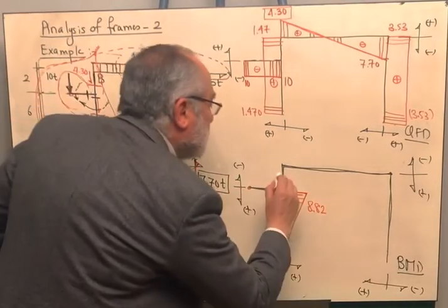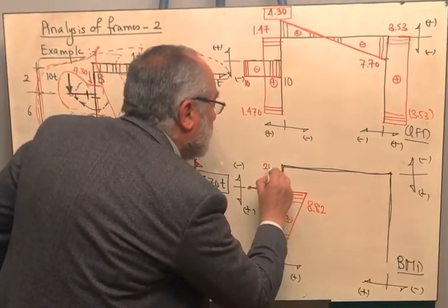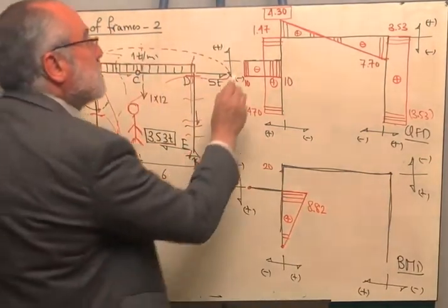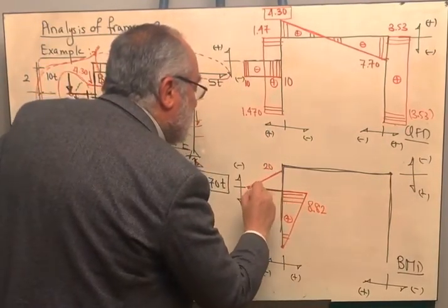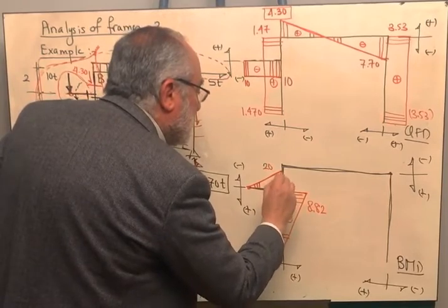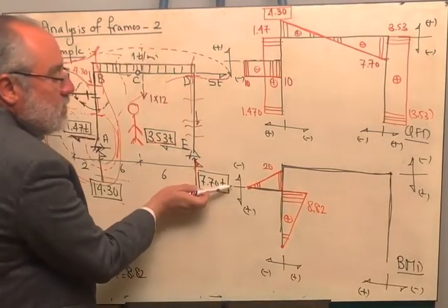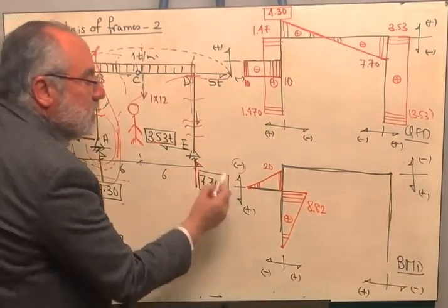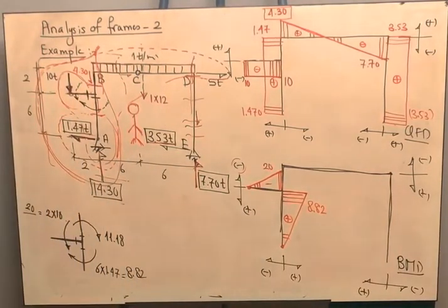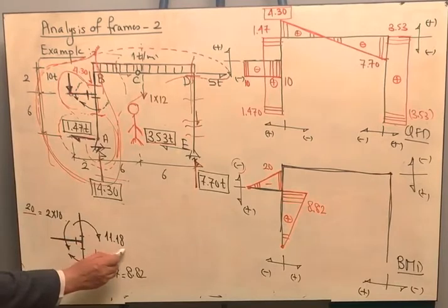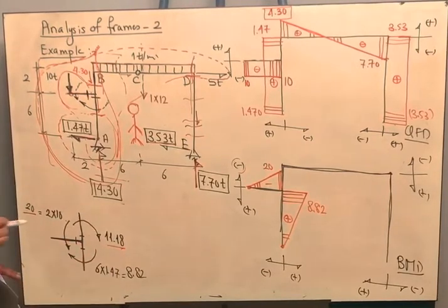So here it will be 20. How do I connect? I am having constant shear, therefore the bending moment is linear. Now the bending moment is drawn above the datum, therefore it is negative. Okay? Now I want to draw the 11.18. Where is the tail of the arrow?